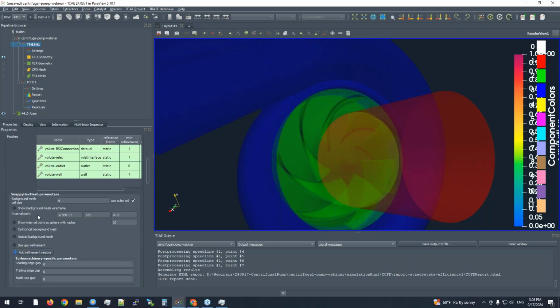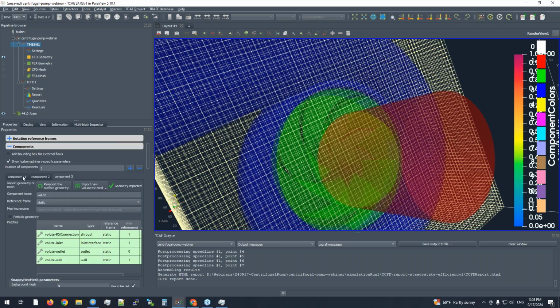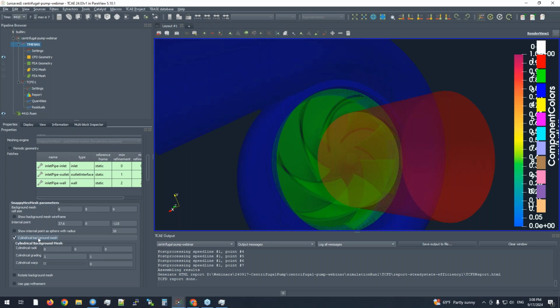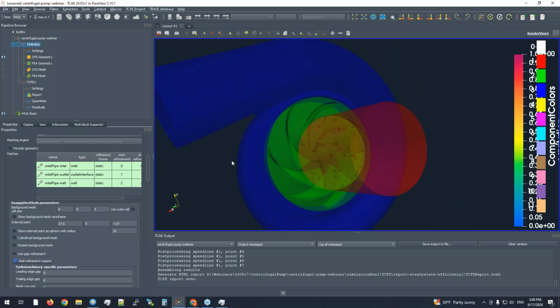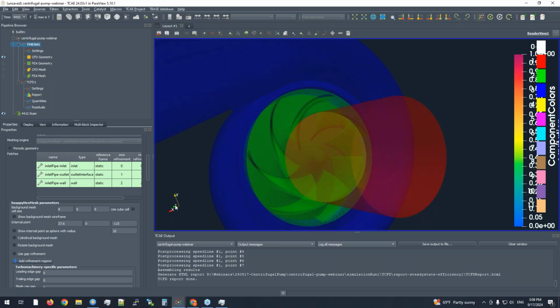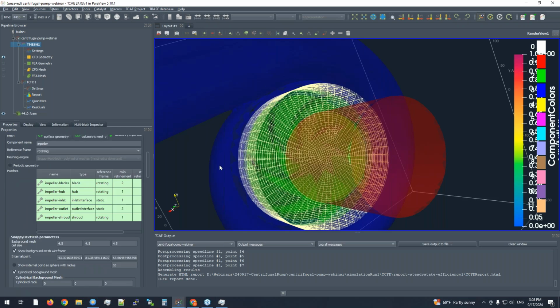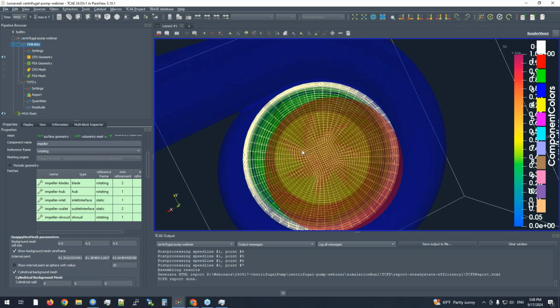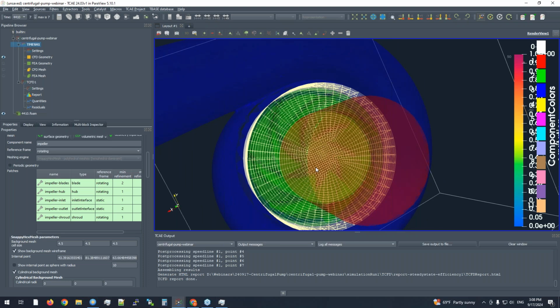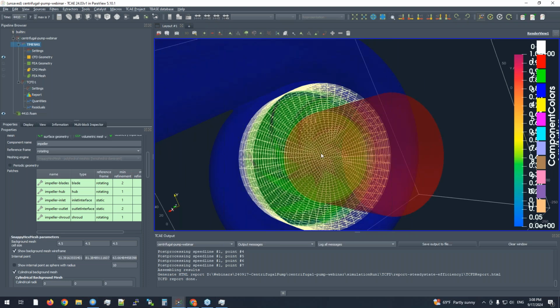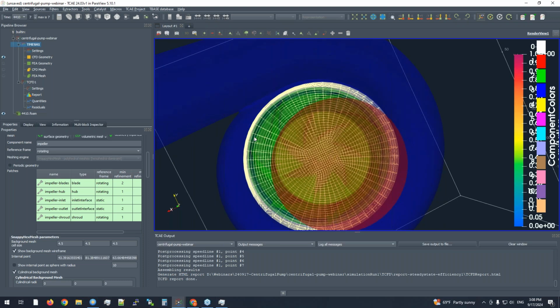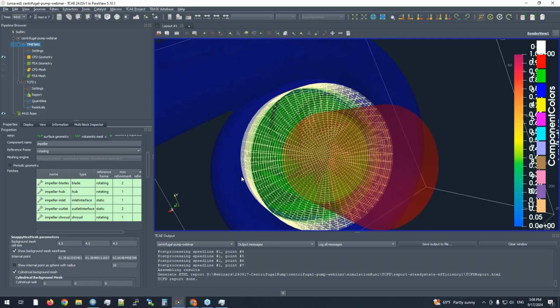It would need maybe a bit more detailed discussion, because as far as I know, we have this option, but we don't use it very often, right? Honestly, what was the reason why we are not using it? Because, for example, for these impellers or radial centrifugal fans, the tricky part is that the mesh is still not fully symmetrical, because it has this topological shape, right? Inside there is the hexahedra, and then the core inside. So the core is not symmetrical. Therefore, I think we applied it for some axial fans with a large hub diameter, where you really have the hole, basically the large hub, and you can really apply this symmetrical part of the cylindrical mesh. For such scenarios, it can be useful, and it can save some count of cells. It can properly fit the hub and shroud contours.